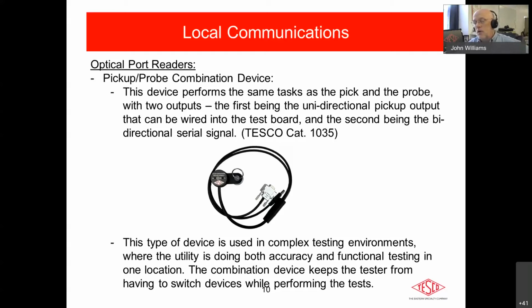And then the USB cable can be brought back to a computer, so that the computer can do the functional checks with the disconnect, with the checking of all the firmware revisions, etc. These are the types of things that are checked prior to deployment for all your meters. So you have one device there that connects to the front of the meter.